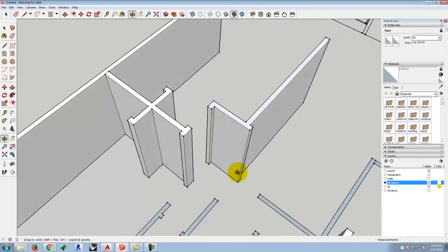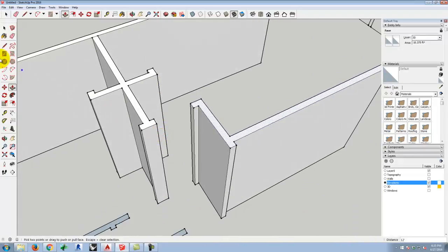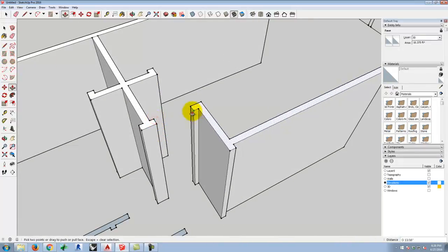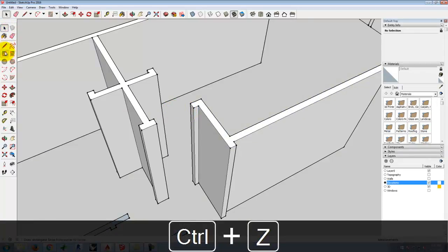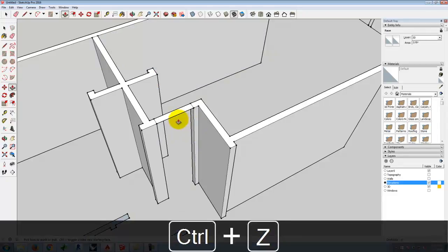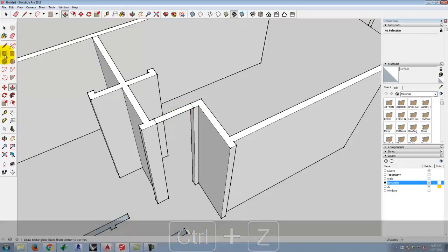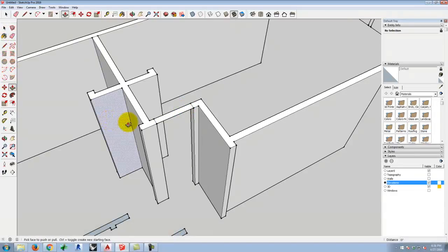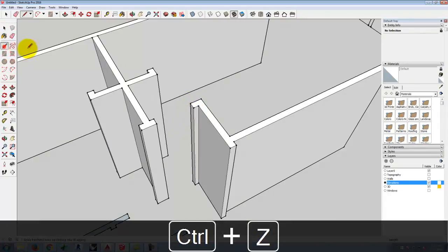Obviously, once I get the walls extruded, I'm still going to have to fill some pieces in. So for example, I still need a top to my door. Oops. So let me use my rectangle tool, and I'll put a top across. Now in this case, I'm going to push-pull the opposite direction. So if this goes down that way, I can fill it in. Sometimes SketchUp has issues with the direction that you're pulling. And you saw that briefly when I went underneath. It wanted to go the opposite direction. If that's the case, we can flip the faces afterward, or instead of drawing it there, I could go down a certain distance first.